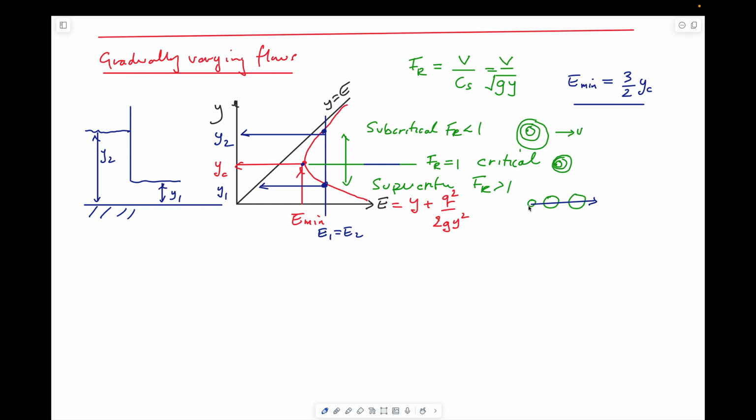If you drop a pebble where the Froude number is greater than 1, then the ripples as they go downstream get progressively larger, but they're carried by the advection flow within the water. And if they're right at criticality, Froude number of 1, then they wouldn't be able to travel upstream because it's trying to travel upstream at exactly the wave speed. So that's the reason that you get these ripple formats.